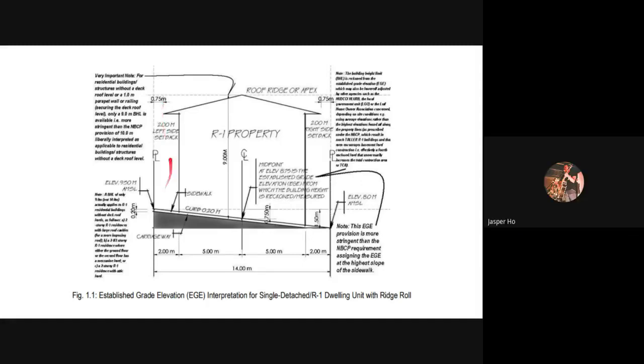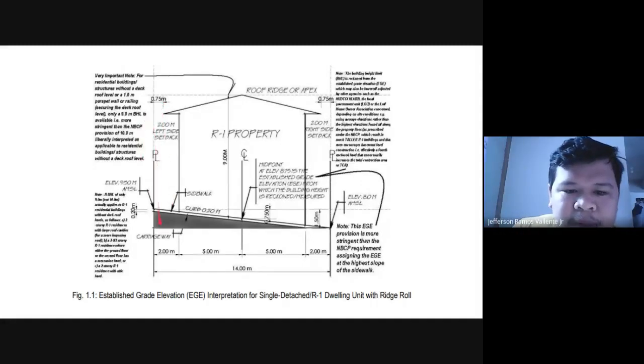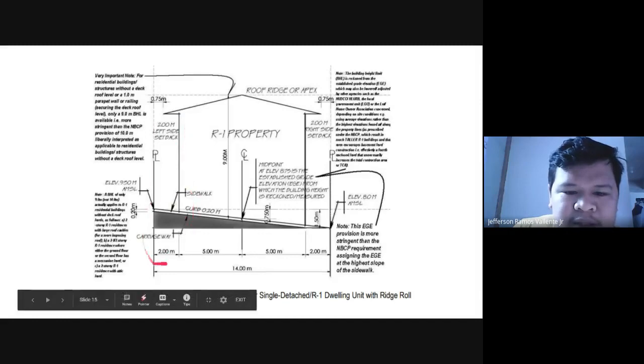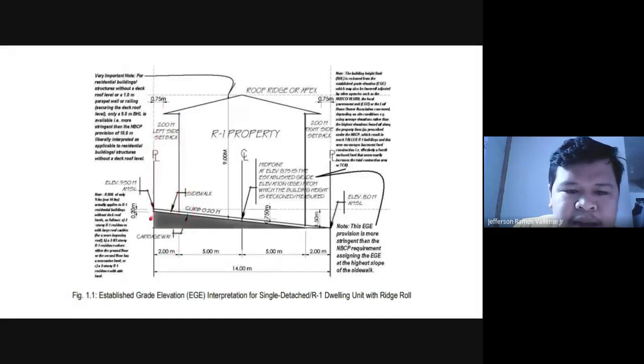Okay. So, the 2 meters is absolute. Per property line, 2 meters, this one. Wall to property line, 2 meters. And from this wall to the next neighbor's wall should be another 2 meters, so 4 in total.